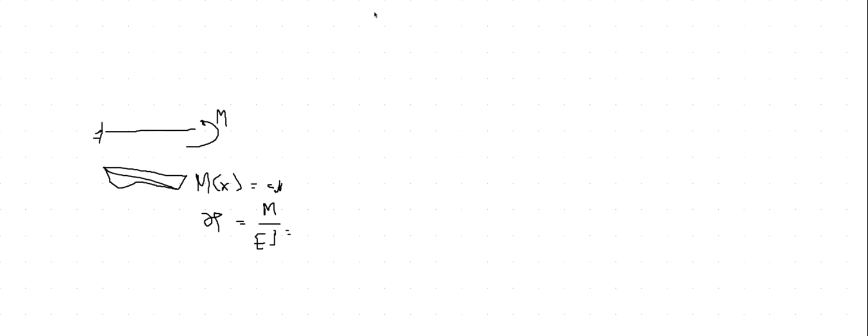So the deformed shape has to be part of a circle where you preserve the same length, and depending on what kind of model you put in, you can build it as a half circle, or as a full circle. For example, if you take this to be equal to EI divided by L times, let's say, pi, this will be this configuration here.